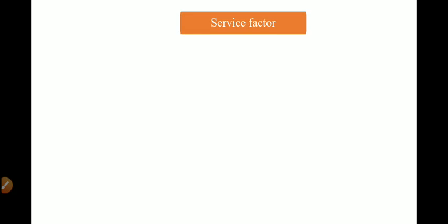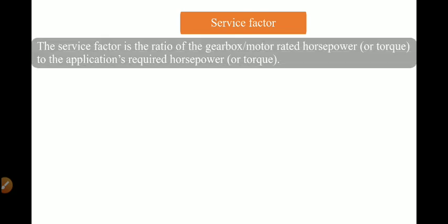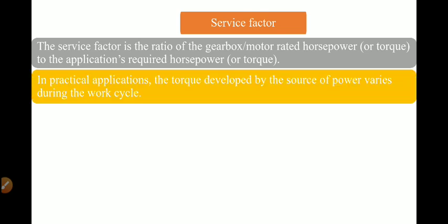Service factor. Again, one more important topic is service factor. And what is the service factor definition? The service factor is the ratio of rated horsepower or torque to the application's required horsepower or torque. Power is either provided by gearbox or by motor. That's why the definition is: the service factor is the ratio of gearbox or motor rated horsepower to the application's required horsepower. In practice, the torque developed by the source of power varies during the cycle.